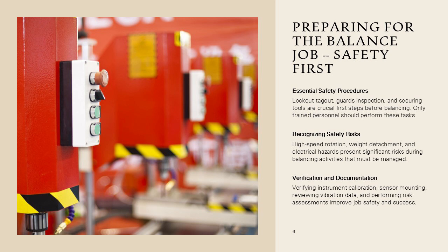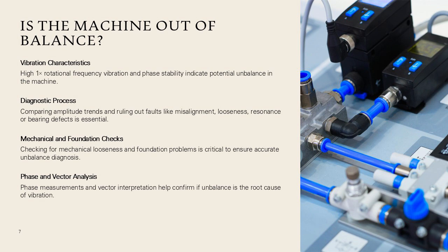The slide also emphasizes the need to verify instrument calibration, ensure sensor mounting integrity, and review historical vibration data. Safety-first preparation reduces risk and increases the likelihood of a successful balance job. This slide explains how to determine whether unbalance is actually the root cause of observed vibration.